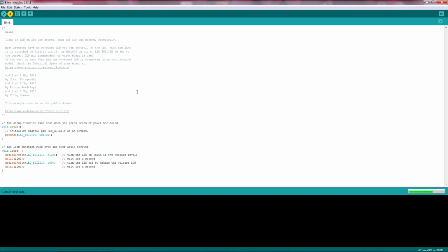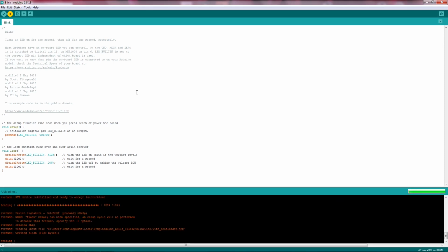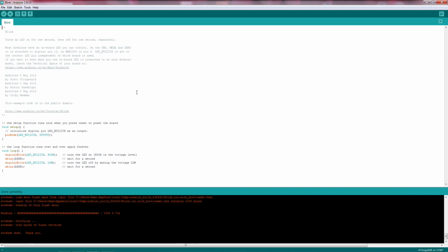Now, there is something very important here. The microcontroller isn't actually configured for a specific crystal speed, and the microcontroller cannot determine the speed of the crystal. The speed of the crystal is a property entirely of the crystal. So if you put an 8 MHz crystal there, then the microcontroller is going to be running at 8 MHz. It's not going to be running at whatever speed it decides to run at around that. No, it's going to be what the crystal says. That's the whole point of the crystal. They set the speed in a very precise way.